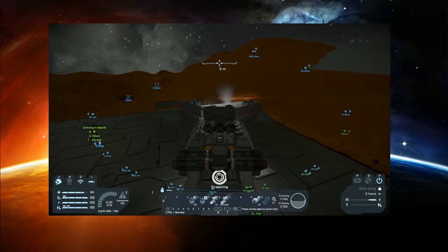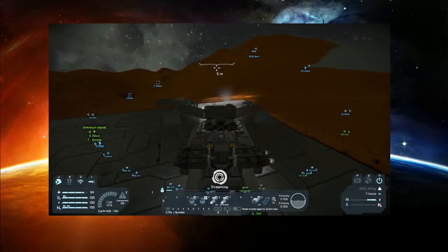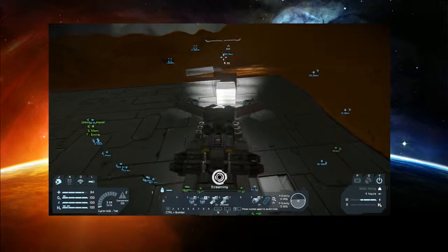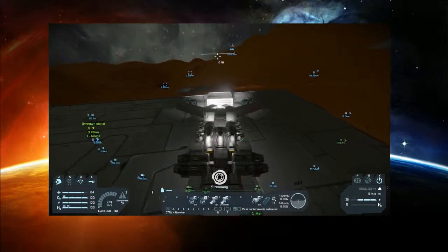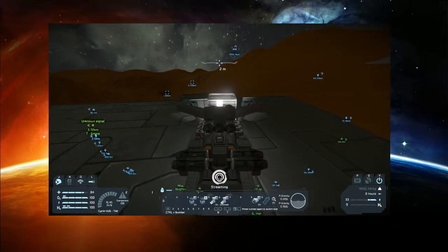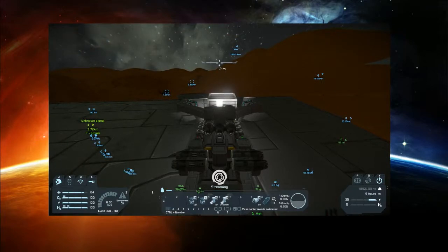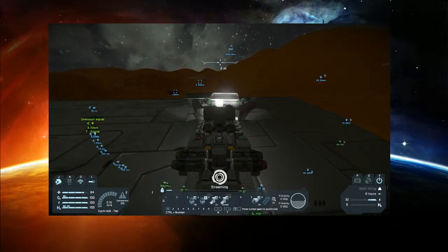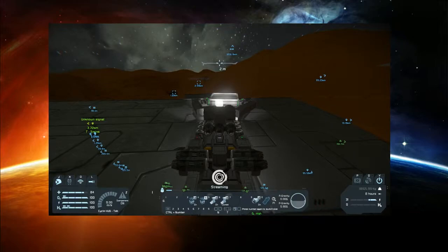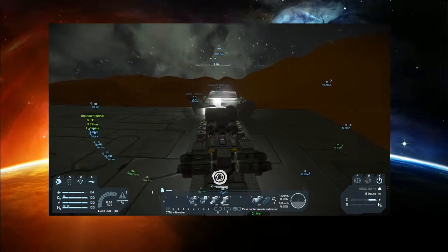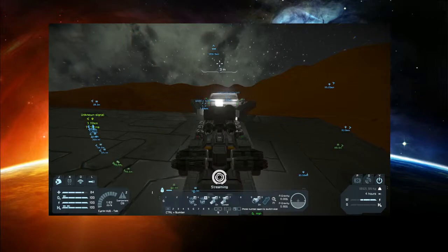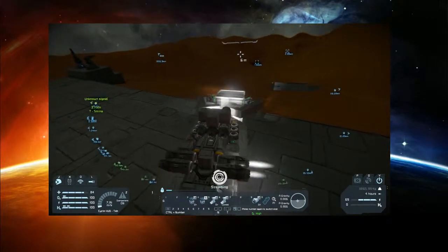Just wait for that to open. Right, lock. Okay, now we go up to the item we want to move. Let's just say this. Put this here for this. Now, we want to reverse the motors and unlock the rotors. And see the landing gear lock on, or one of them did. There we go. And now we lock them before we move anywhere, or it can have some wobbling issues like that. So lock. Now you can move it, take it to wherever you want it to go.